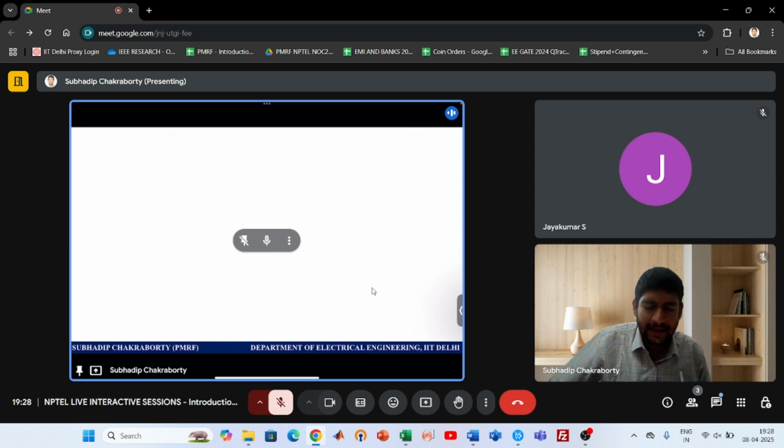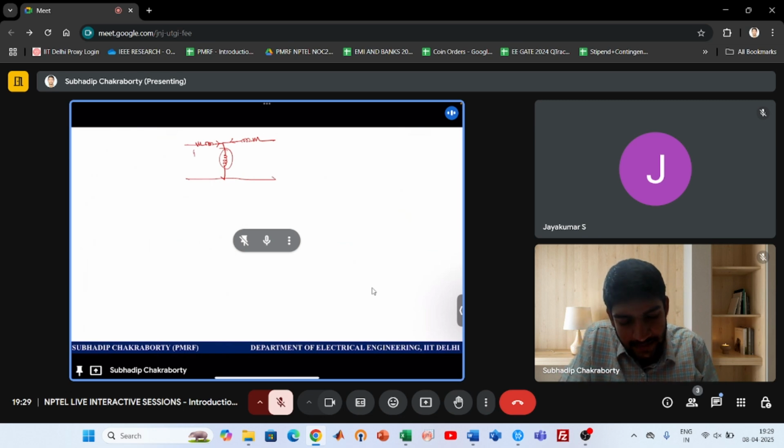Okay, that is clear. But please understand that you had a magnetizing branch, which is nothing but the mutual branch denoting the flux linkage mutually from the stator side as well as from the rotor side. That was the whole purpose. So this was primary, this was secondary, or this was stator, this was rotor, and this was the branch where the induced EMFs take place.